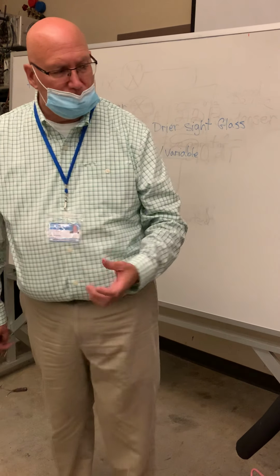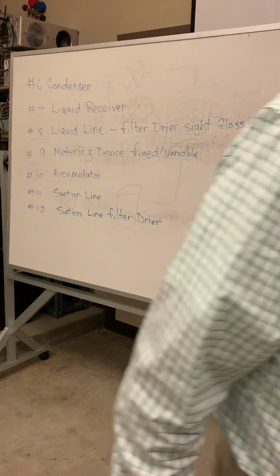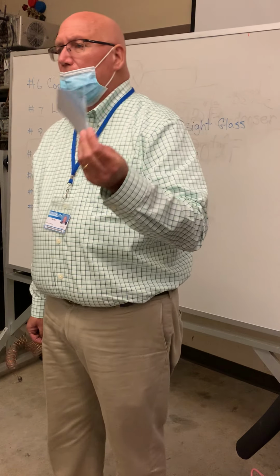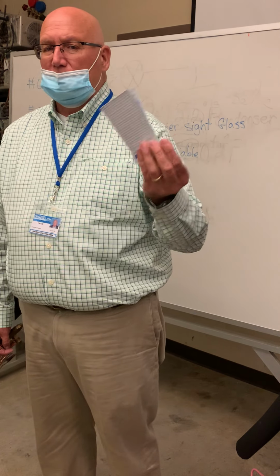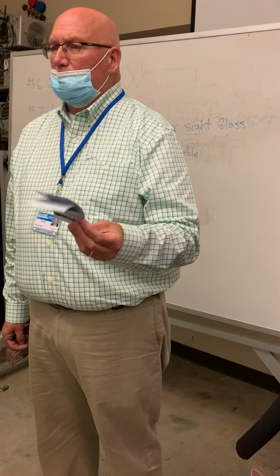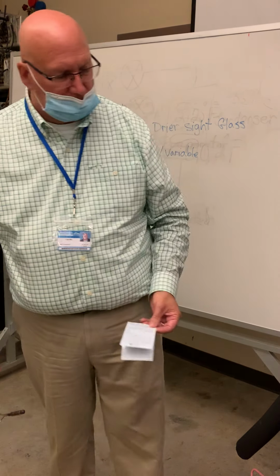And I can use my pressure temperature chart and see 40 degrees Fahrenheit, R22, what's that corresponding pressure? Always, whether it's using R22 or R410A as its refrigerant, it will always be 40 degrees. The pressures would be different, but it'll always be 40 degrees.